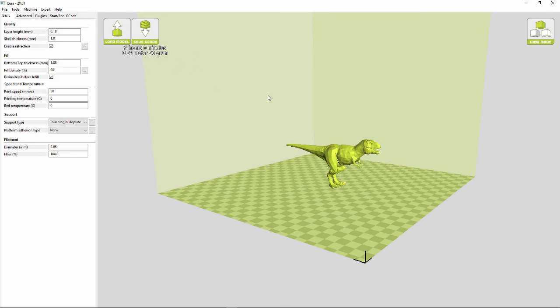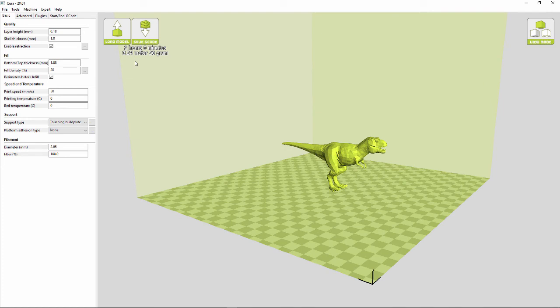I'm going to go ahead and load our printing profile that we're using right now with our TAZ 5. We're printing with a polyester, which is a product called Engine. That's the filament that we're using. So I'm going to go to first expert and full settings. That's the first thing that you want to check on Cura, is to make sure that we're on full settings.